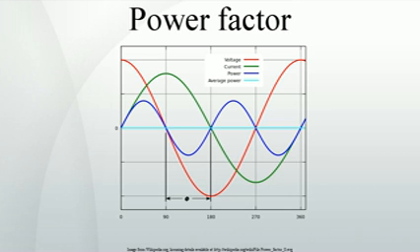During each cycle of the AC voltage, extra energy, in addition to any energy consumed in the load, is temporarily stored in the load in electric or magnetic fields, and then returned to the power grid a fraction of a second later in the cycle. The ebb and flow of this non-productive power increases the current in the line. Thus, a circuit with a low power factor will use higher currents to transfer a given quantity of real power than a circuit with a high power factor.